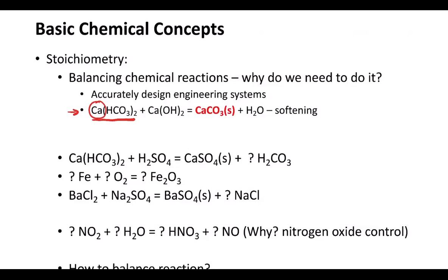So as I said, it's an interesting approach that people use to solve this problem. Actually, people introduce more calcium ions into the water to reduce the calcium ion concentration. But what's actually taking place is the reaction between the bicarbonate ion and the hydroxide ion. So the bicarbonate ion can react with the hydroxide ion to form water and carbonate ion.